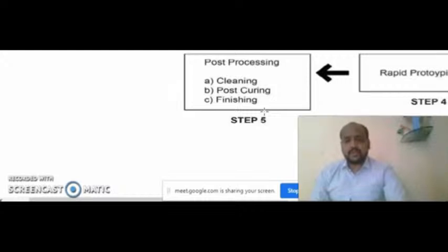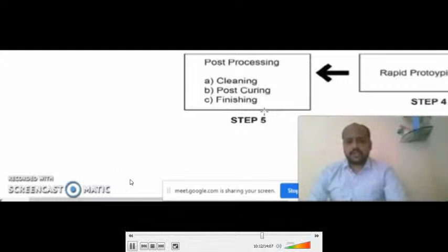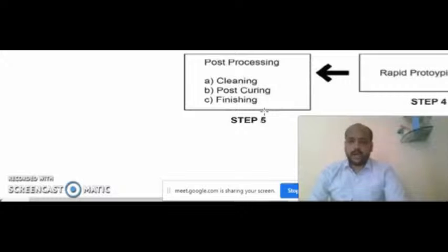The model must be solidified properly, otherwise its shape may change or it may break after 3D printing. So we have to avoid change of shape, and we have to give sufficient time for the model to solidify.